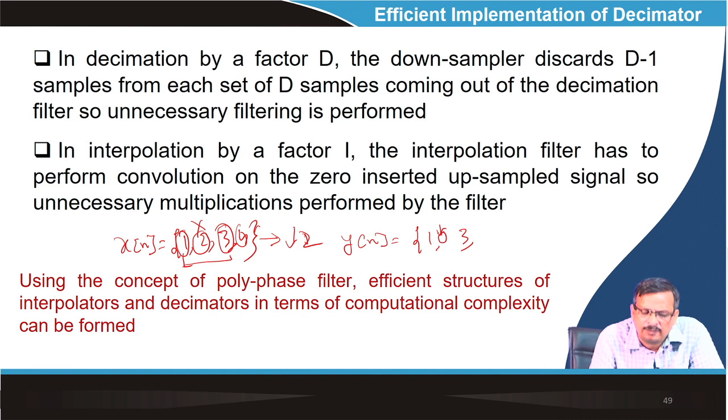So, why should I include that coefficient during filtering? Because it increases the order of the convolution. The complexity of the convolution depends on the length of the signal. Now, due to the downsampling, the length of the signal is reduced. So, why should I use the whole length of the signal for filtering? How can I efficiently implement the filter such that the samples which I am discarding I will not use?